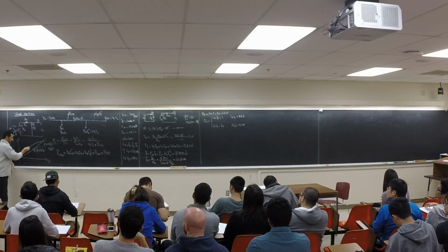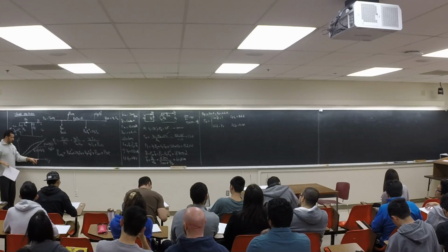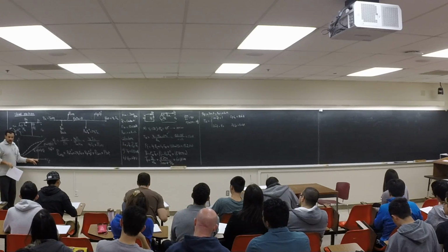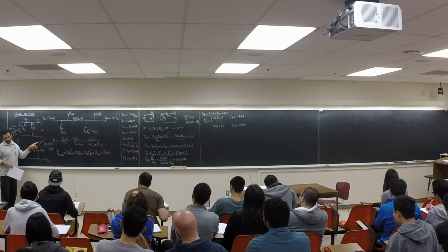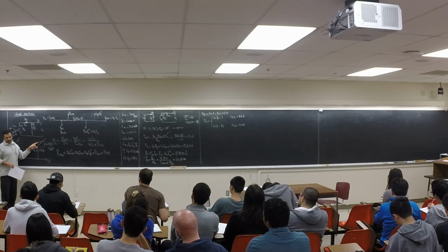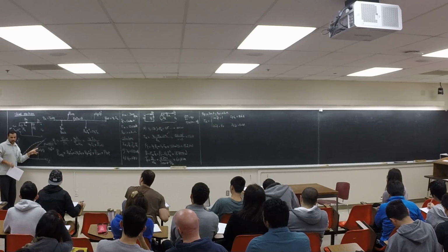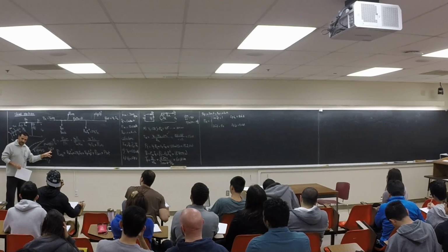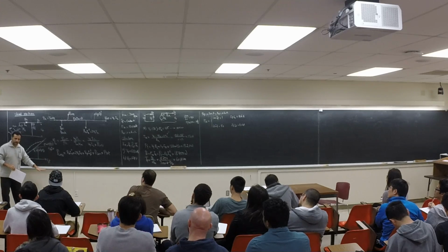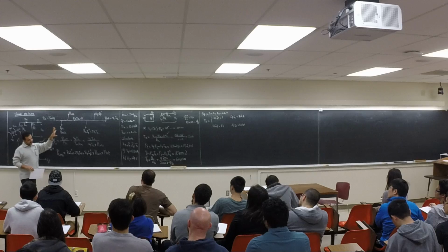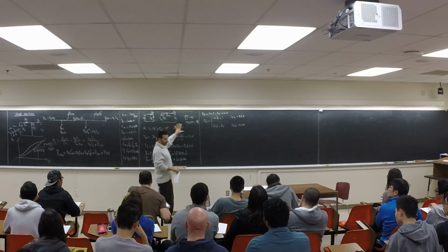For the same IF, say 1 amp, rotating at 1000 RPM this much voltage will be generated. If I rotate at a lower speed, the voltage will be less, because I'm keeping IF constant and KF is a constant. So this curve is given for a specific speed. But in this example, it looks like we didn't need it.